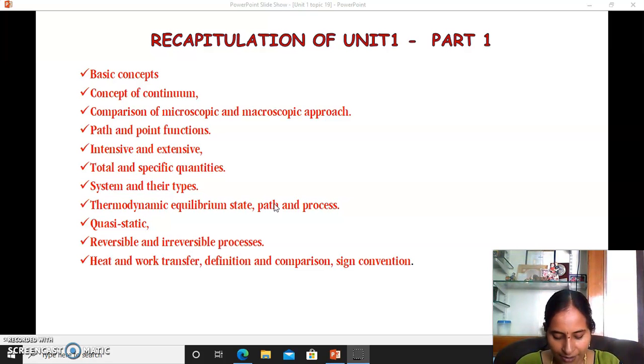Work done by the system is taken as positive, and work done on the system, that is, absorbed by the system, is taken as negative. Heat flow into the system is taken as positive, and heat flow out of the system is taken as negative. The salient features of heat and work are that both are energy in transit, and can be identified only during the course of interaction, while crossing the boundaries. They are boundary crossing phenomena.